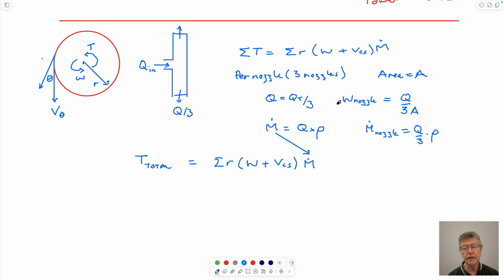The velocity out of the nozzle would be this. The velocity is the same out of every nozzle, so it's just this same amount. The mass coming out of the system is the same as this. You could do it by calculating this per nozzle and doing the mass flow rate out of each nozzle multiplied by the velocity. Or you could do it in the ensemble, I guess, being a fancy word.